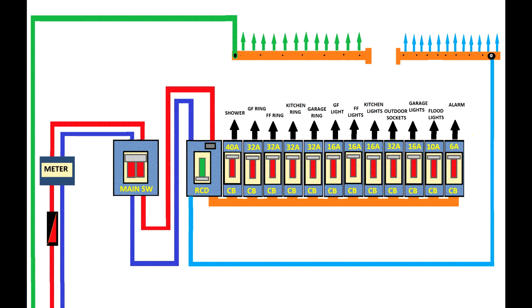So now let's see how we can identify the faulty circuit in an easy way. You'll observe now that your electrical system developed an earth leak. There's an earth leak between the ground floor lighting circuit and the earth. An RCD trips if the earth leak exceeds 30 milliamps, providing electrical safety and reducing the fire risk.